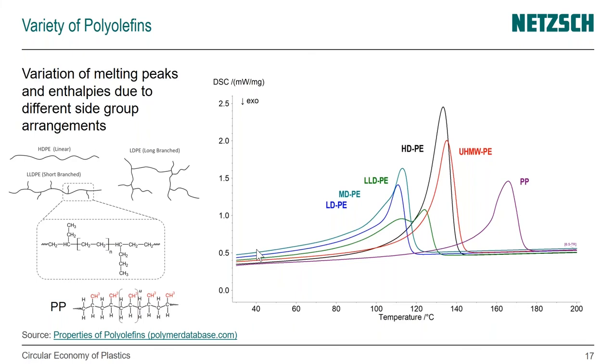With the DSC, that is not so easy, because you don't necessarily want to start degrading your material. That could have an effect on the sensors in your DSC. So you have to be more careful with that, to just heat it up to 500, 600 or 1,000, depending on the DSC you have. This could very well have an effect if degradation happens and it condenses on the sensors, things like that.